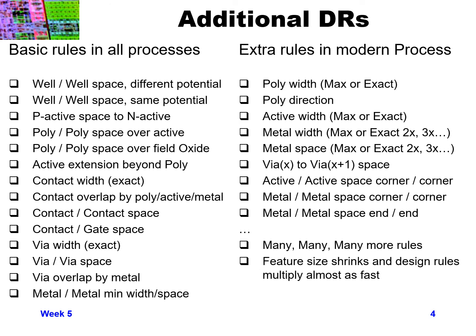So the thing to keep in mind is, as modern process technologies have been shrinking dimensions because of things like the mask technologies that we're using, where we're doing optical proximity correction of the masks, they have caused many side effects that create many more design rules, and things have gotten much tougher in actually drawing your different layers because of these design rules.